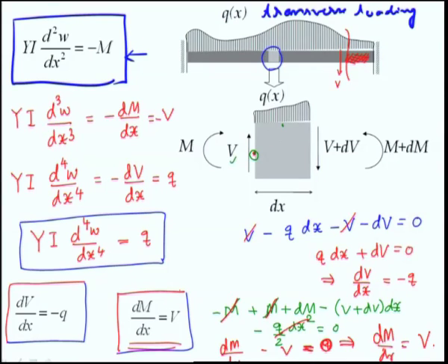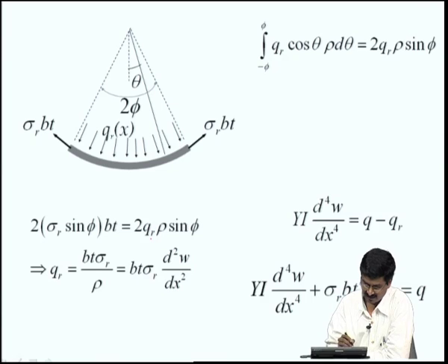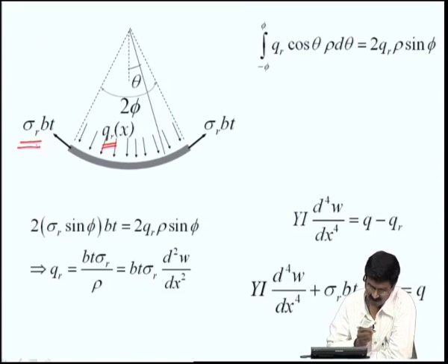Okay. So, having derived this general relationship, now we want to find q related to this equivalent residual stress. Okay. So, for that let us take a little segment which we have denoted here, which has bent because of residual stress. Okay. Let us say that QR that is shown here. So, the QR that you see, there is a little r over there, that is acting on the beam in the transverse direction, and we say that QR causes this residual stress sigma r.